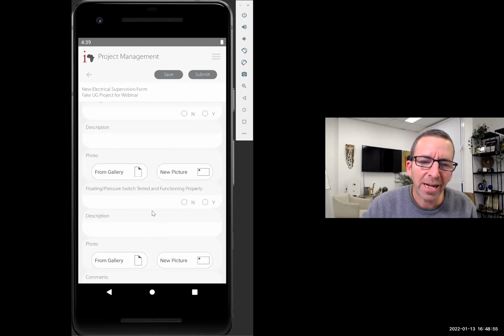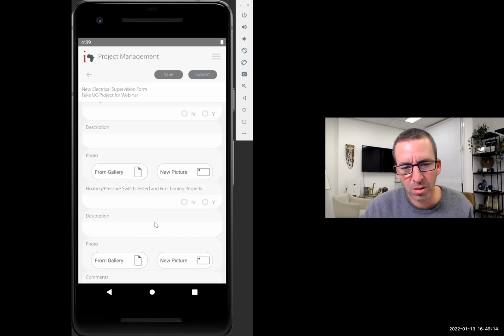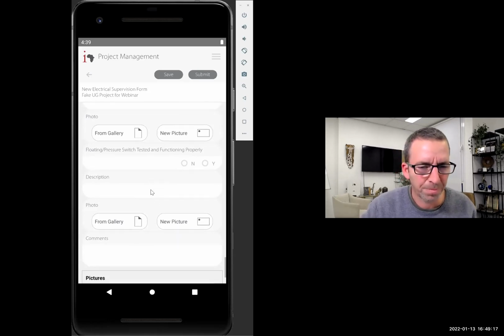It also means that after the floating or the pressure switch disconnects the pump, you need to open the taps to see the water going out, and you need to measure the amount of water that went out when the floating or pressure switch disconnected the pump again and returned it into work. So that's another thing to check.